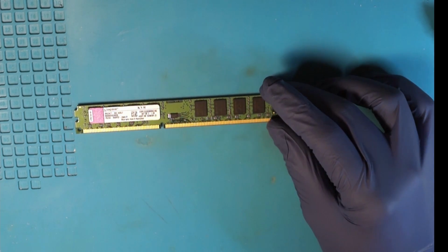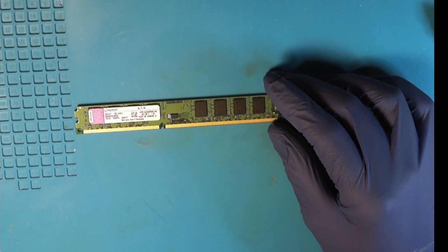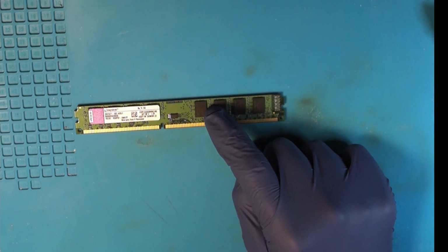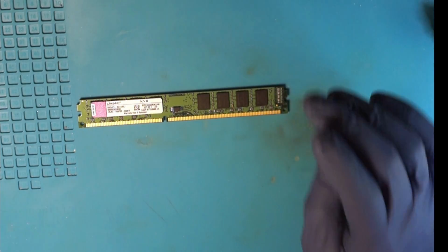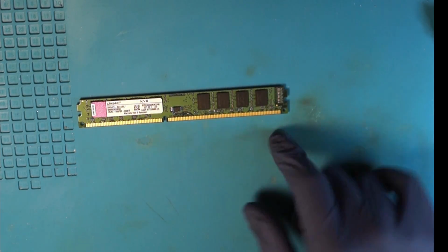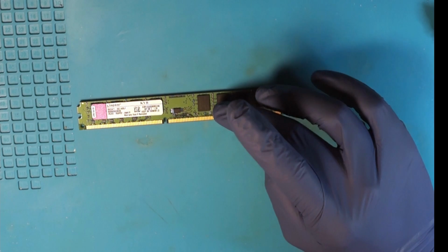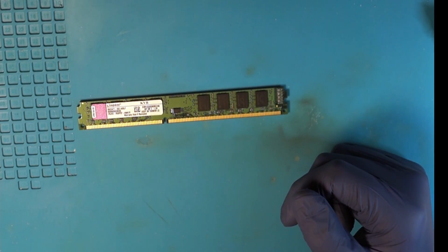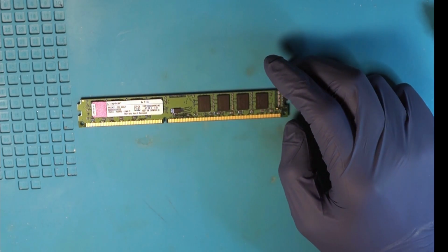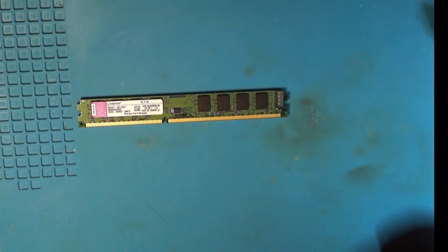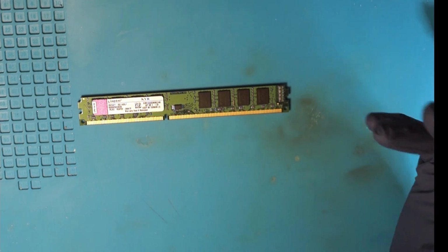And we want to change a few or quite a lot of details in that when we upgrade the memory chips on a DIMM. We want to change the density, obviously, of the chips. We want to change timings, because I upgraded from 1300 to 1600 mega transfers. We also can change manufacturer, part number, serial number, timings, yeah, quite a lot.